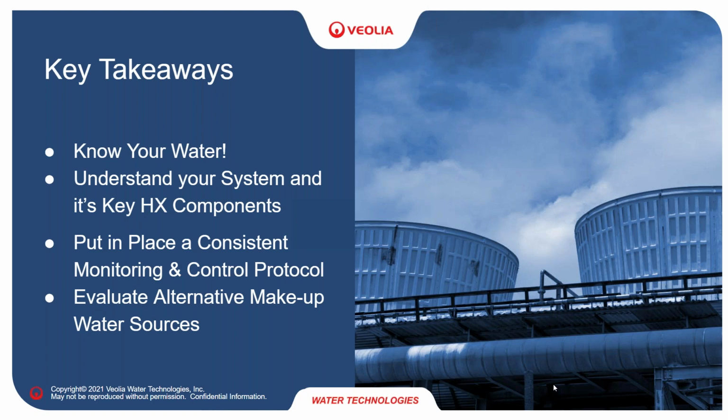And finally, we spoke briefly about the alternative makeup sources that are available for cooling tower operators. We reviewed the benefits and potential challenges of changing the quality of the water in the cooling system. While providing a home for reclaimed or recycled water, a well laid out plan and control strategy must be developed to ensure that you're not endangering system integrity, the reliability, or the efficiency by introducing a different quality makeup.